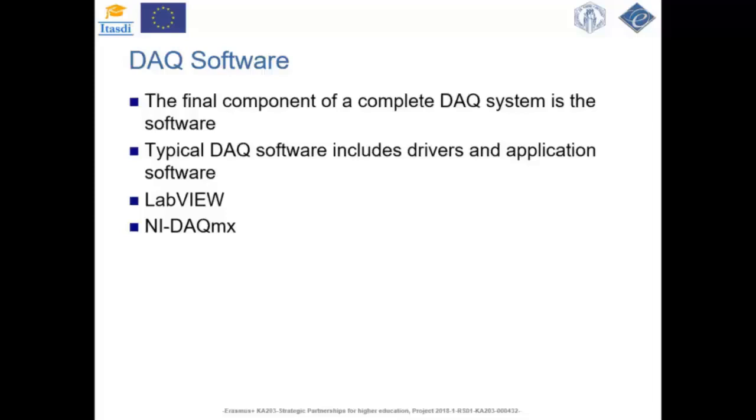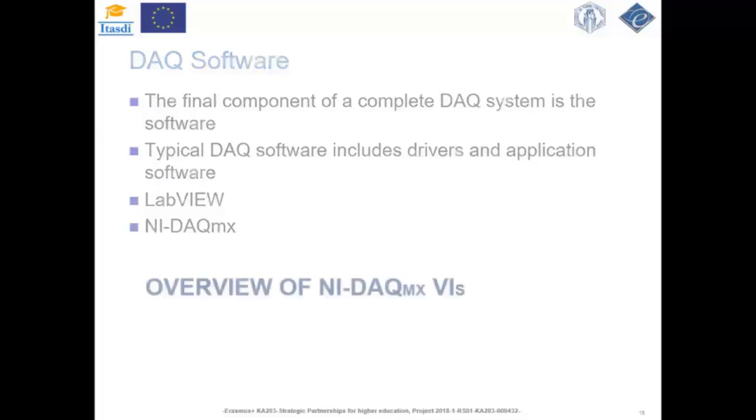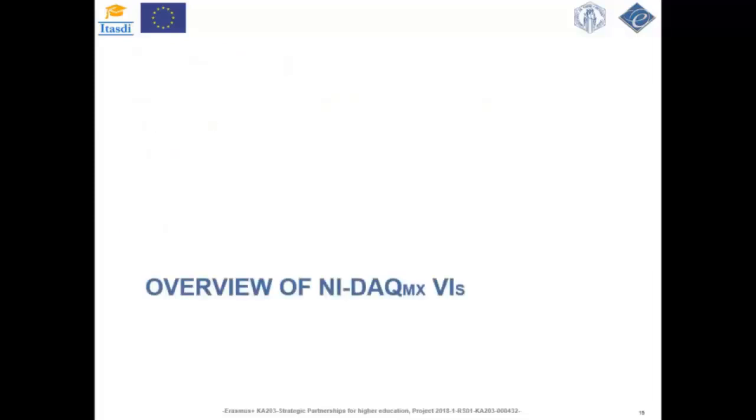So, National Instruments measurement devices include the NI-DAQmx driver software, which is a collection of virtual instruments or functions used in LabVIEW that are used to configure, acquire data from, and send data to the measurement devices. The NI-DAQmx software is used to communicate with National Instruments DAQ devices, and it provides a user interface and a set of tools for programming and configuring your data acquisition device. So now we're going to take a close look at the NI-DAQmx virtual instruments.